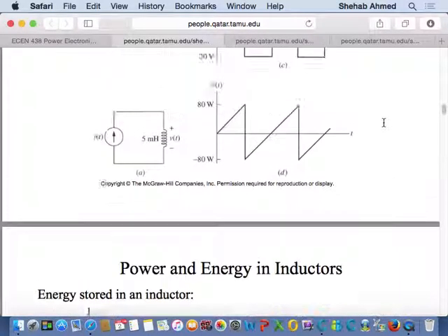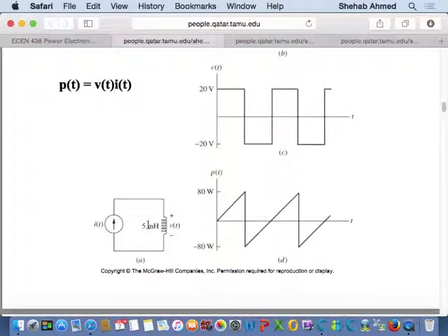There is instantaneous power, right? Is there instantaneous power being delivered from the source to the inductor or not? Yes, there is instantaneous power. I mean, there is power going from the source to the inductor. But what happens is the inductor is actually giving that energy back to the source during this part of the cycle. Okay? So there's an exchange of energy between the source and the load and vice versa. Power is going back and forth, but there's no average power being consumed. So if this was a battery, for example, it will never die out. Even though there's current, it will never die out.